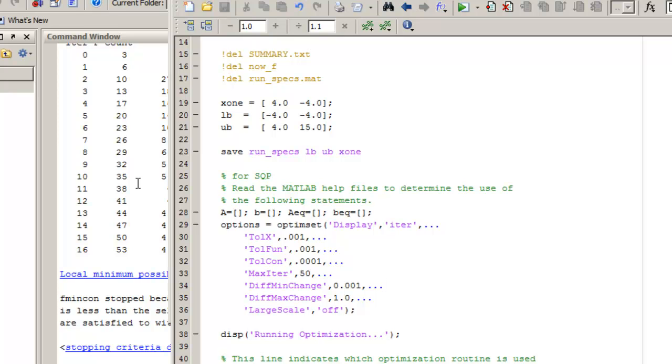If you have many locations that your optimizer ends up in, sometimes that's not a bad thing, because optimization isn't really about finding just one solution. It's about understanding the design space better. And sometimes you might find local minima that are not necessarily global minima, but are in much more interesting design locations. And that's one of the many things design optimization engineers look for when they're running their studies.